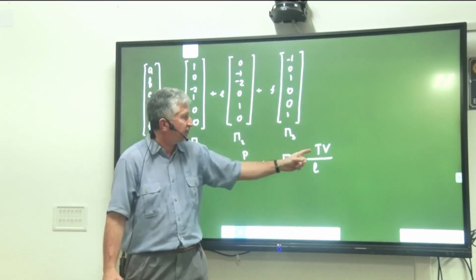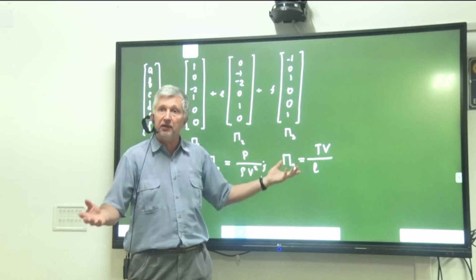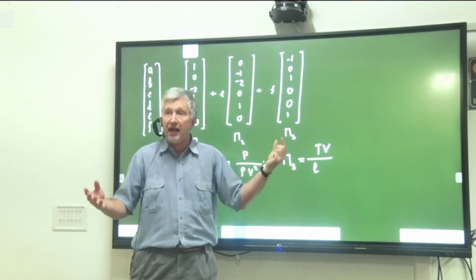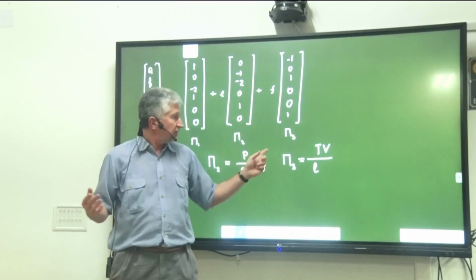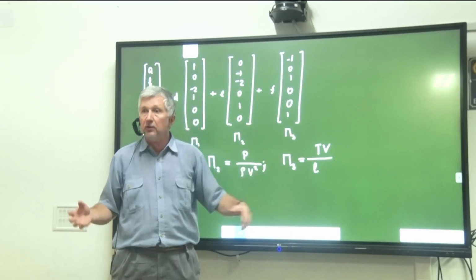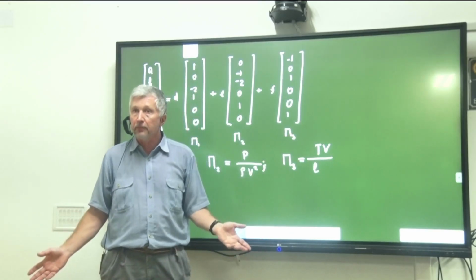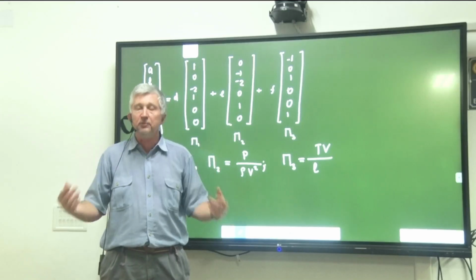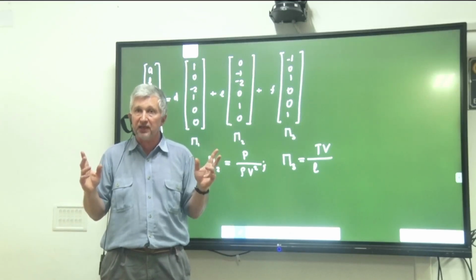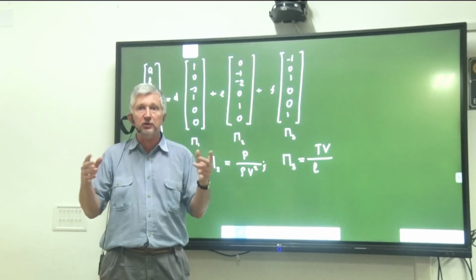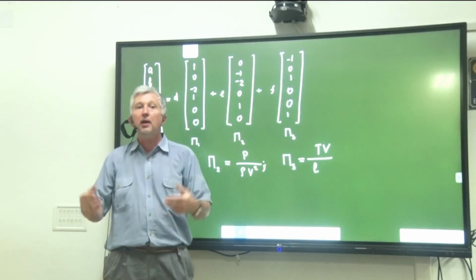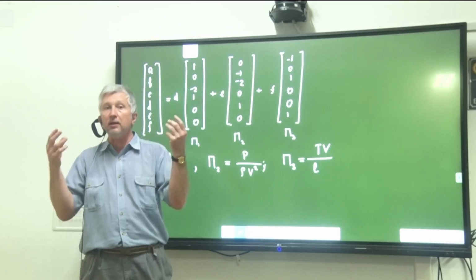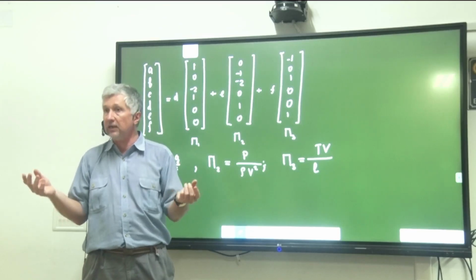For example, if V becomes twice as large, but so does L, then this ratio here will still remain the same. And therefore the solution which I obtained for the first computations will still be valid, the non-dimensional, scaled solution. All I need to do is take this non-dimensional solution and extract individual quantities out of there and multiply them by their respective scales.